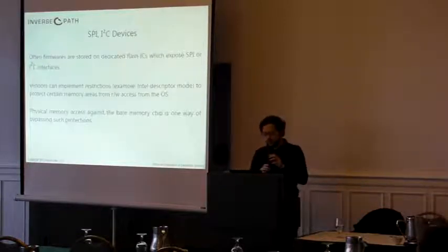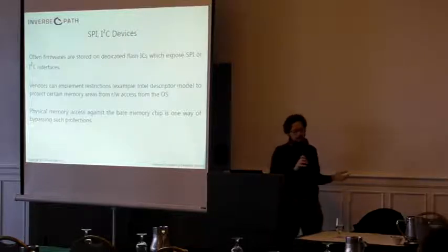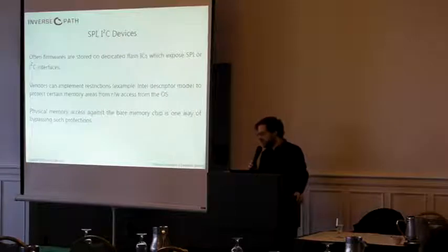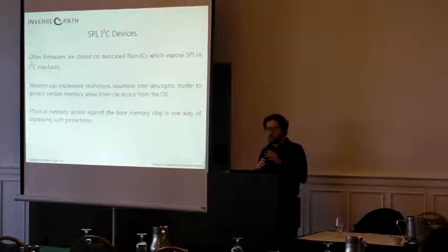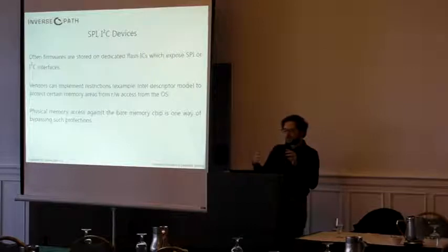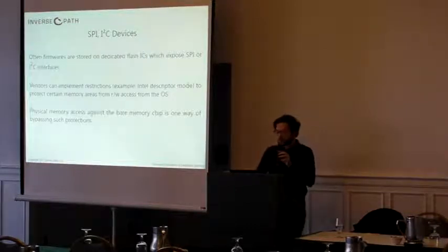scanning techniques. So other than JTAG, and if you're not dealing with a system where you have heavy encryption on the memories, of course the easiest thing is to identify the memory and desolder the different flash memories that are available.